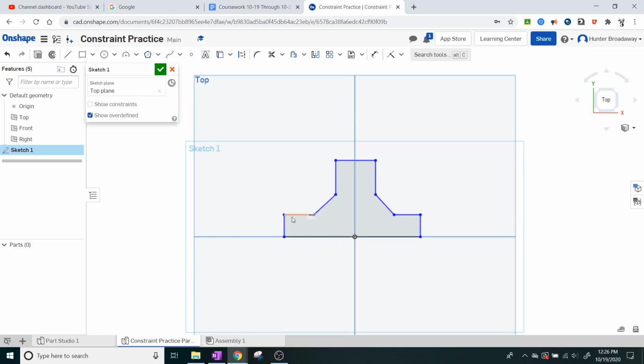Like this length is definitely longer than this length. So all of these constraints that you can see, these little buttons that show up to the side whenever you move your mouse over the lines, these are automatic constraints that are put in place. The one with a line and the other line next to it and a dot, that's a coincident constraint. The line that goes up and down, that's a vertical. And I didn't put these constraints in, they just were automatically there as I was laying them out. Any horizontal line that you lay is normally going to automatically include the horizontal constraint.